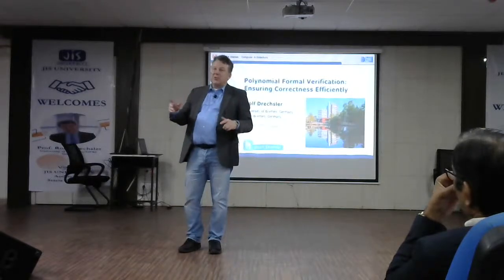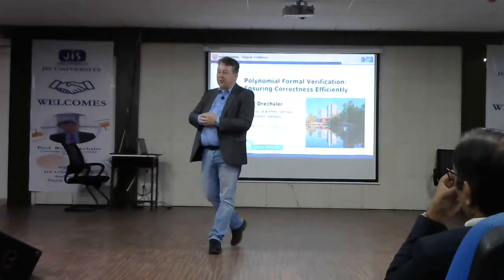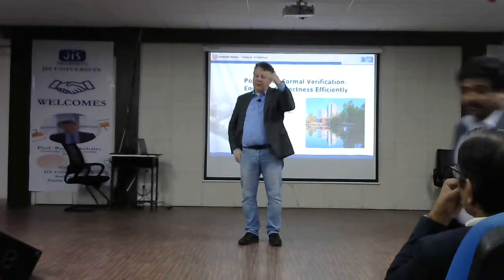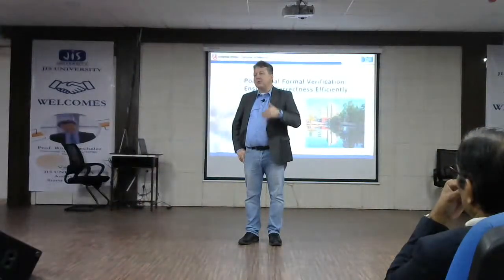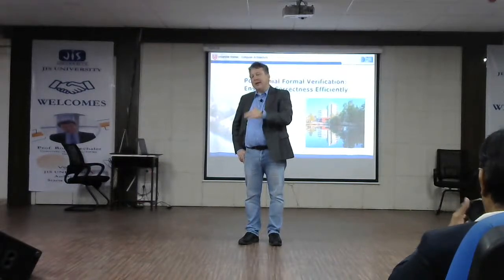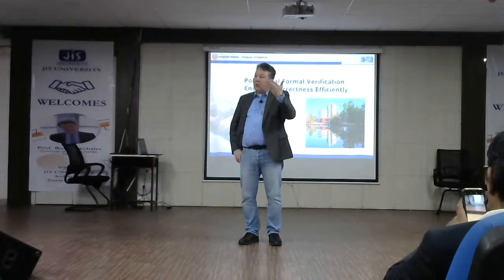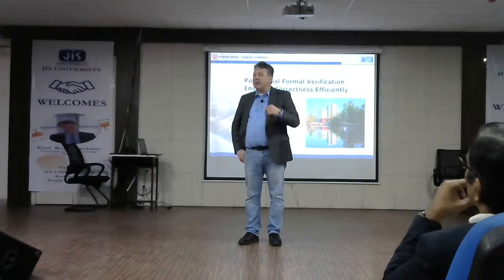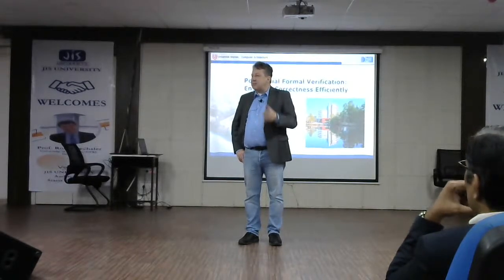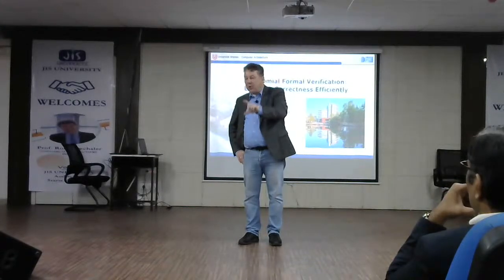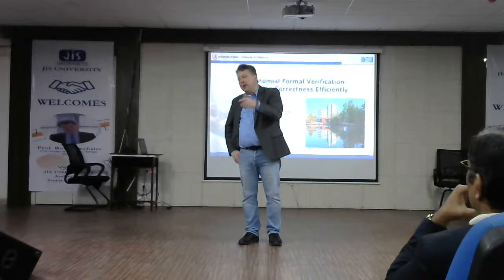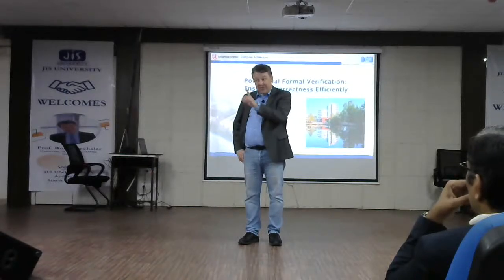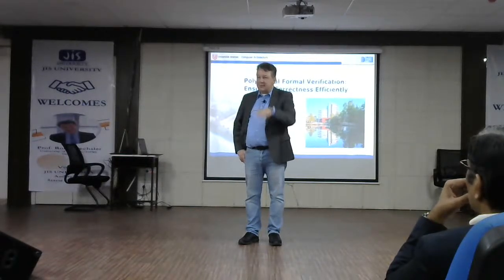So that's why, of course, these days we also apply many of the formal techniques and combine them in a hybrid fashion with some kind of software structures. For example, you use mutation-based testing, concolic testing, and also fuzzing, the techniques that people from the software world use. By this, for example, we were able for RISC-V architectures to identify bugs in operating systems, where we combine symbolic techniques with partial symbolic simulation and testing techniques. But then still you cannot get 100%. It's a very relevant problem, and that's why we are also working in this direction.